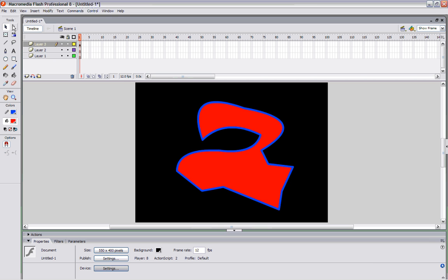Let's talk about the sub-select tool. That tool gives us the ability to look at all the points in our drawing. If I double click this little box, I get these little grips that allow me to change individually the look of the line. So this line from this pick box to this pick box changes. If I select it, I get this pick box and it changes. You can see the grip changing here.